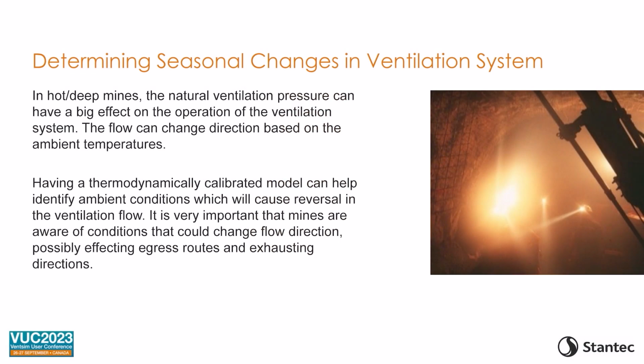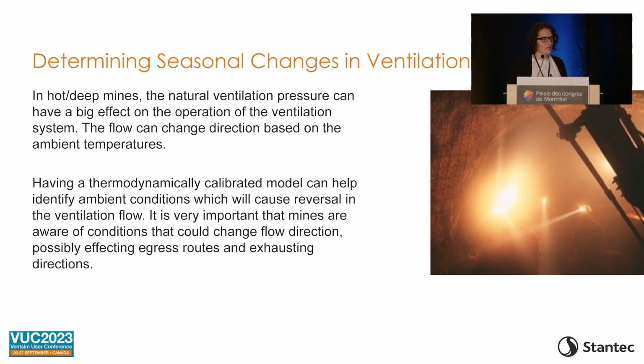Then my last operational benefit is the seasonal changes, and this is especially important for deep mines or mines that rely on natural ventilation pressure to ventilate them. Recently we had a mine that we were working on, and they were seeing the flow reversing in one of the tunnels because it was getting cold. And to satisfy regulatory requirements, you should know which way the airflow is going.